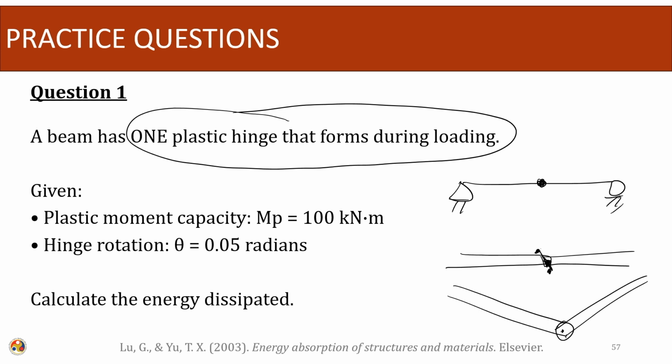In case of a simple structure, we define the plastic hinge such that if we cut the cross section out here and look into the beam, then the entire region has undergone the plastic regime. In the cross section, as we increase the load, the maximum strain will start to form.